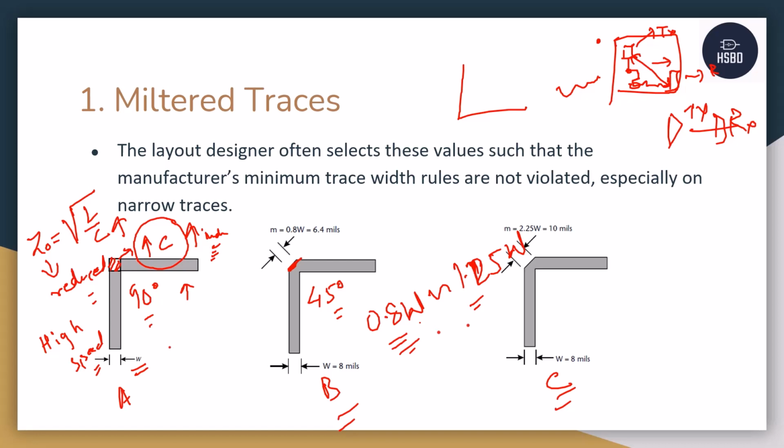If you use this method, you're never going to see any impedance discontinuity here. So the signal is going to flow like this in the traces. Let me just brief it up again. The guideline that we talk about here is, it shouldn't be 90-degree, it should be 45-degree. I'm talking about the high speed designs. I'm not talking about the low speed.